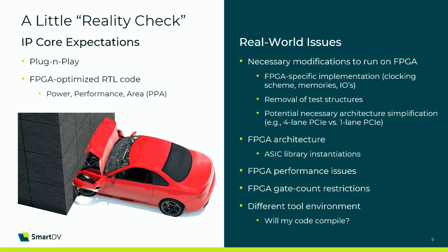The last bullet that we see here is regarding the tool environment. As ASIC IP cores are typically synthesized with ASIC synthesis tools such as a Synopsys design compiler or Cadence tools, they might cause issues when being run through FPGA synthesis. Also, this has to be taken into account. And this little reality check that we are doing here gives us the answer that it is not as easy as one would expect to import an IP core that was originally developed for ASIC and now is ported to the FPGA structure.